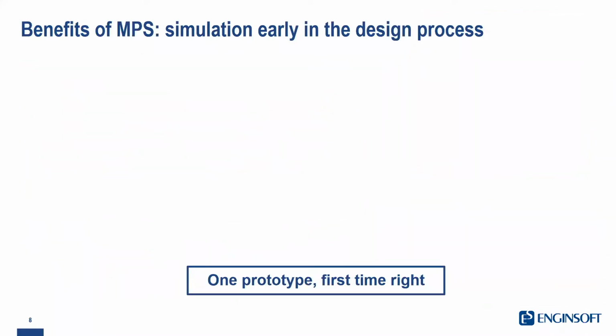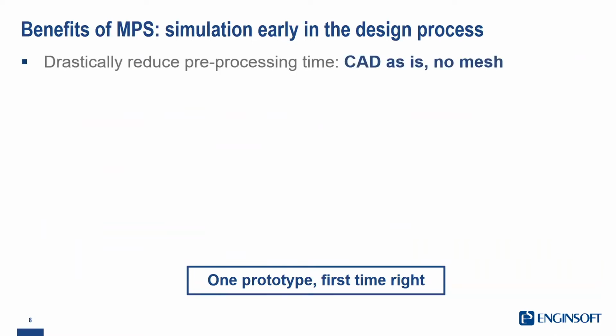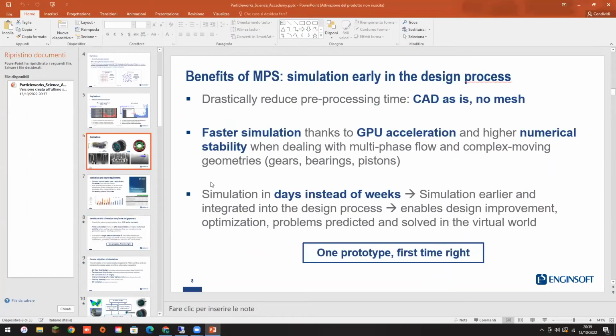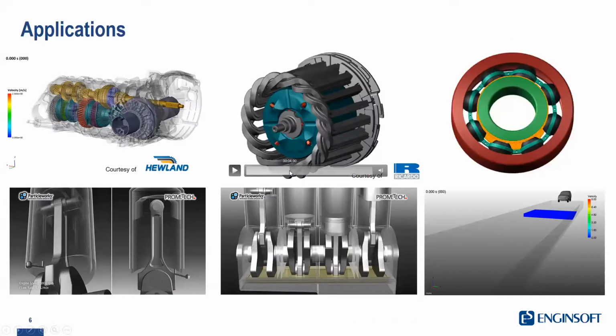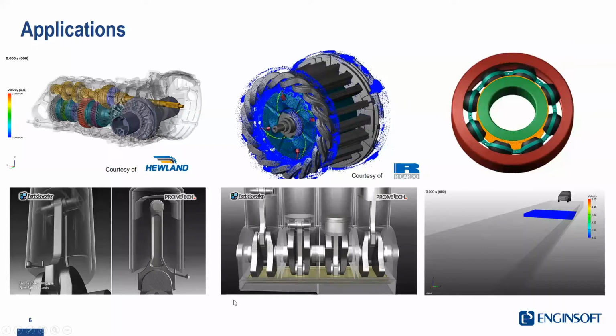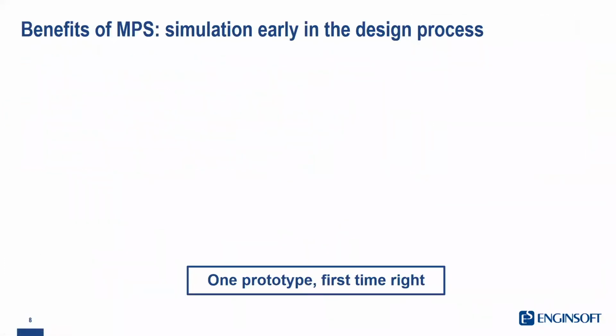So Particleworks is used because a new type of cooling system is applied. Actually, sorry, I will just go back to this slide. This is an example of the new cooling system. We have oil jets instead of a water jacket around the stator. We have direct oil jets that impinge on the windings and on the most critical areas. In this way, we have better cooling efficiencies. Since we are dealing with jets, that is why we use Particleworks in this kind of simulation.